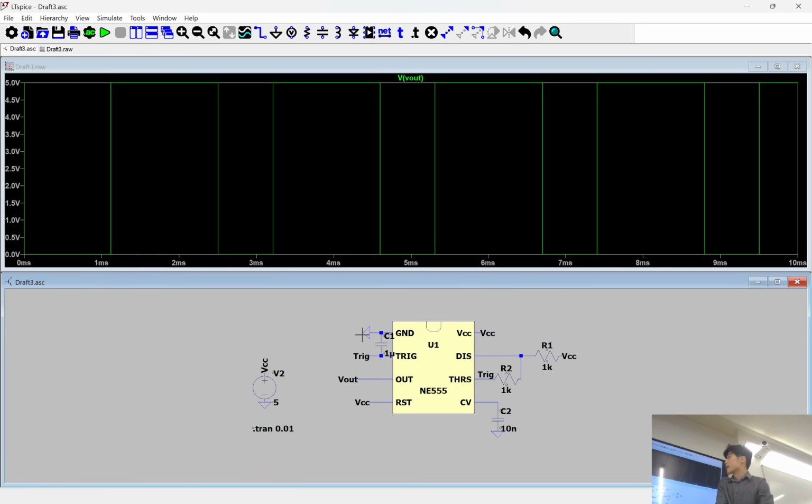And you'll notice here that, as I mentioned, we get a square wave output. Now, pretty much roughly what's happening here is there's kind of a feedback loop, where the voltage causes some of the capacitors to gradually charge and discharge. And then once it reaches certain threshold voltages, it flips over in the opposite direction.